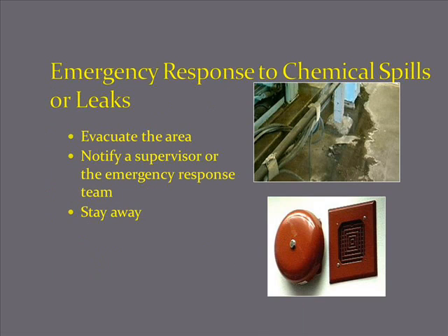Emergency response to chemical spills or leaks. Evacuate the area, notify a supervisor or the emergency response team, and stay away. If you're not trained to clean up chemicals, please do not attempt to do so. It can be dangerous to your health and further prolong the situation.